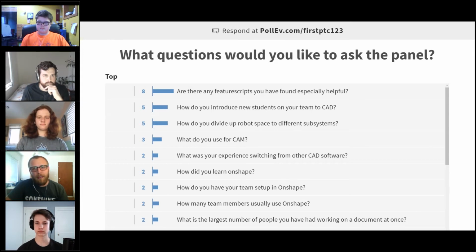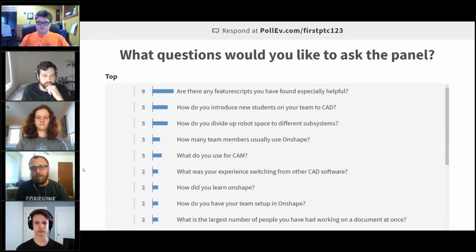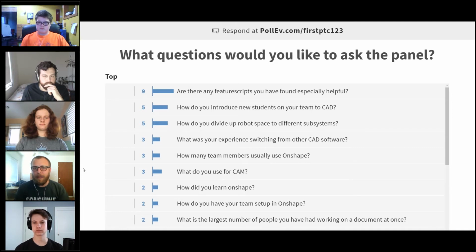But one thing that we've been able to do with Onshape that we weren't able to do with other platforms is, since we assign part numbers to every part, and that's applied both in our parts tracking sheet and in our Onshape document, when there's especially maybe a router part that needs to be made off of a CAD file, rather than the designer needing to produce the DXFs, we've gotten to the point where our manufacturing students are able to have access to our Onshape model and navigate to the proper document and find the part and produce the latest DXF straight from the model.